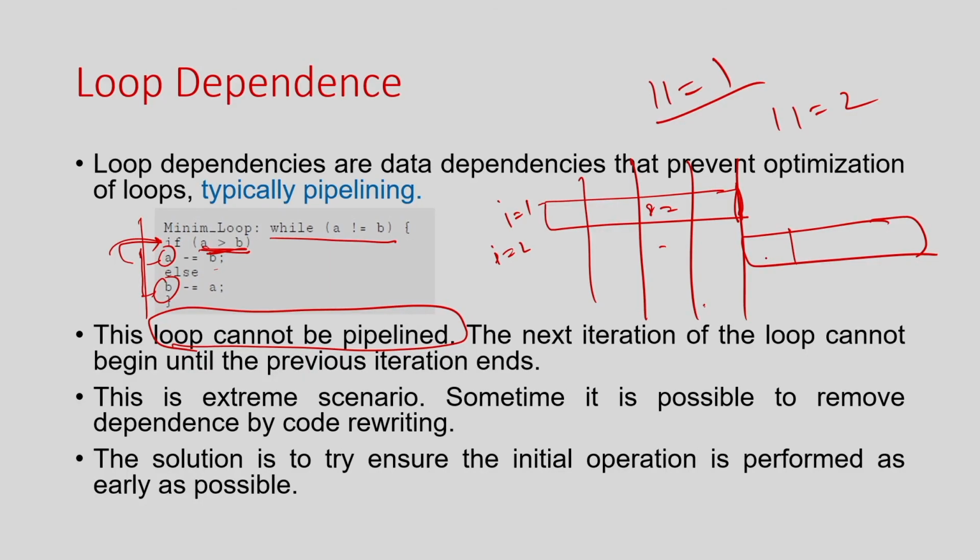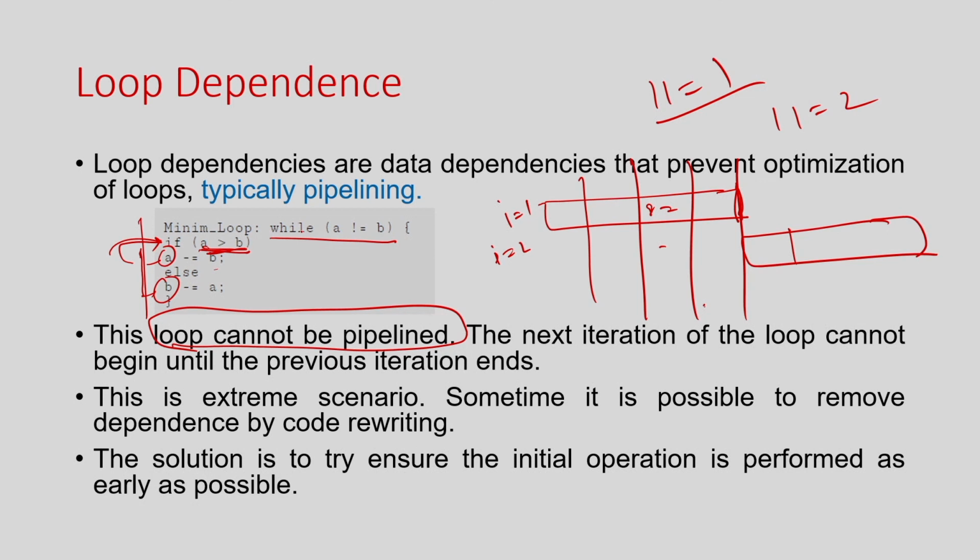That is what I mean. Once we have the program, we may not understand this, but I just apply loop pipelining, say pipeline with II equal to 1, and the compiler will simply report during synthesis that it cannot be pipelined, and I just get a non-pipelined implementation.